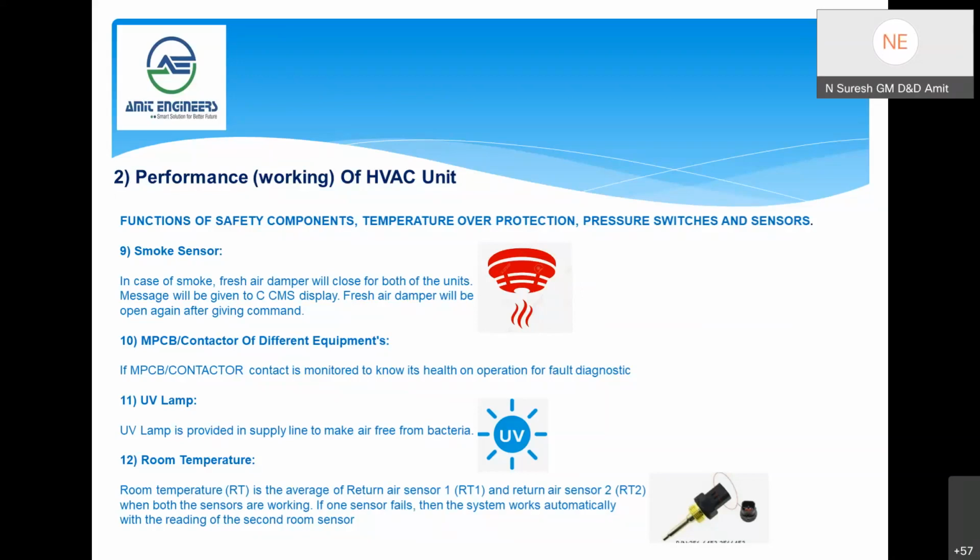Acha, acha. And what is the benefit in case of smoke detection of closing the fresh air supply? If there is smoke outside and we keep taking the fresh air, the smoke also gets into the coach and the CO2 level increases, and the passengers will feel discomfort, and there is also the safety aspect. That's why there is a very sensitive smoke detector. It will sense and close the fresh air. This is the outside smoke detector, so it's outside smoke, not inside the coach.